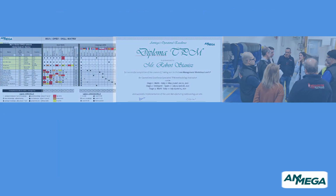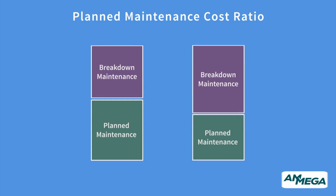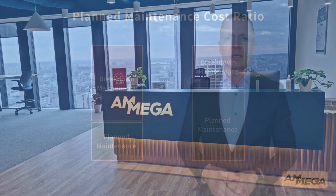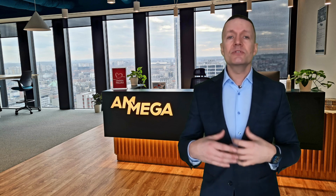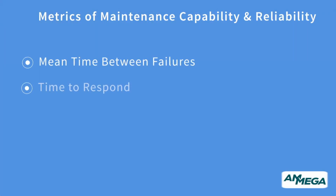For example, the ratio of planned maintenance to breakdown maintenance is a good metric indicating that an organization is developing capability to become less reactive to breakdowns by doing more to prevent and plan our maintenance work. We can measure overall reliability of both equipment and the maintenance function by using metrics such as mean time between failures, time to respond, and mean time to repair.